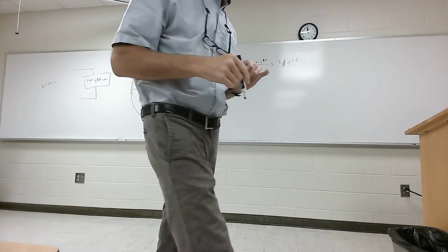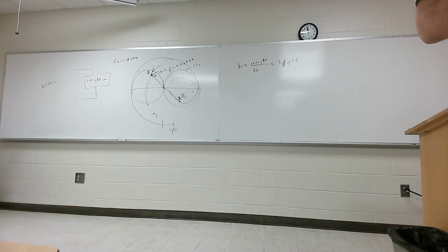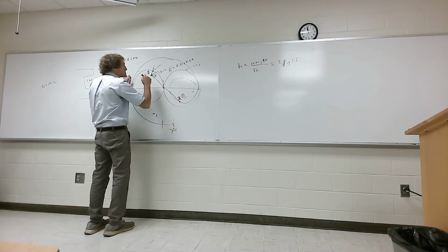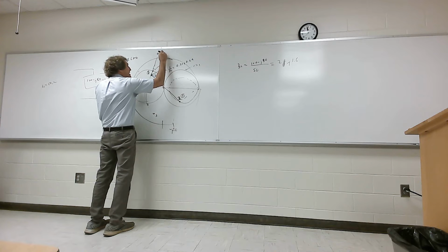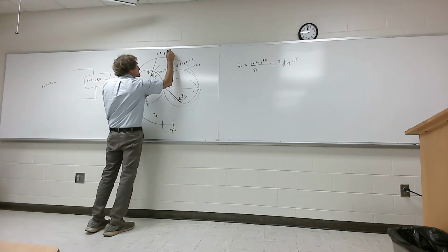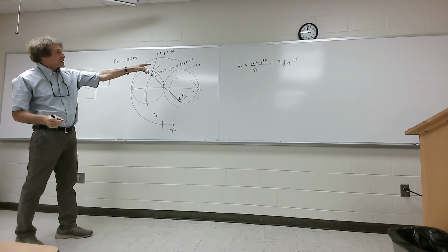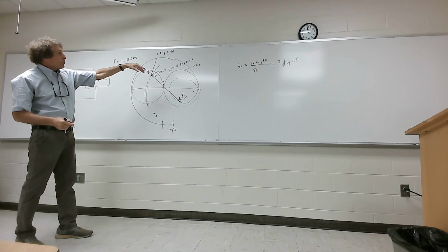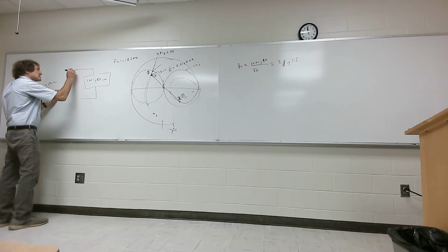Look it up on your chart, you've got one. You can probably enlarge that and really see. So what do you get? 0.46? So it's 0.3 right here, 0.3 plus J, what is it? 0.46. All right, so that means I have to go from J 0.24 to J 0.46, right? Y'all with me? So what is that? That's 0.22, isn't it?